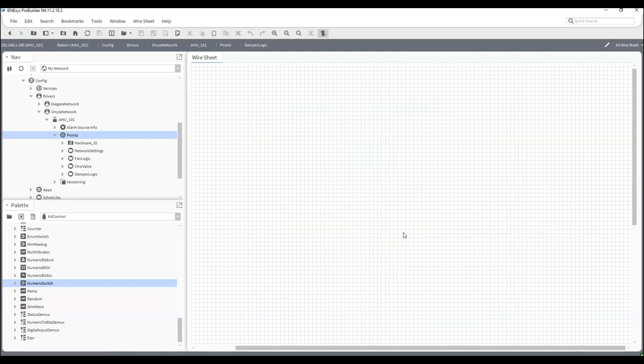And as I go to this folder, I need to figure out how I want to control my outside air damper and my relief damper. Without a building static pressure sensor, the relief damper can actually just follow the same signal as my economizer dampers, because my economizer damper, the outside air, and the return air damper are linked together in this scenario. So effectively, whatever the outside air is doing, the relief damper can also do.